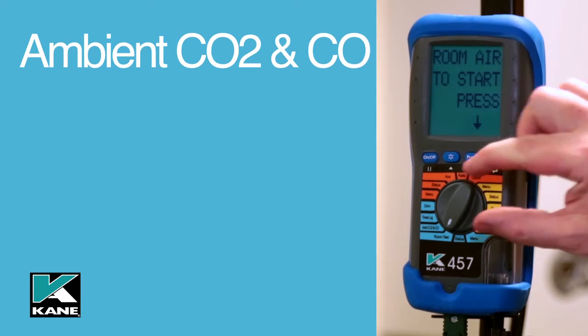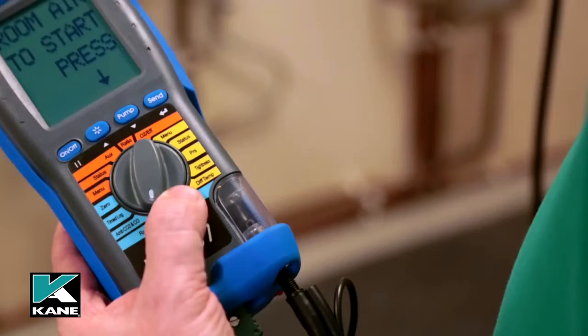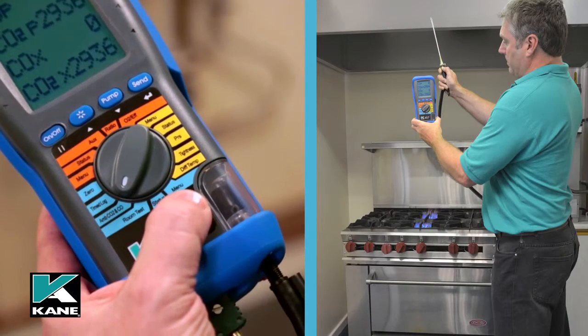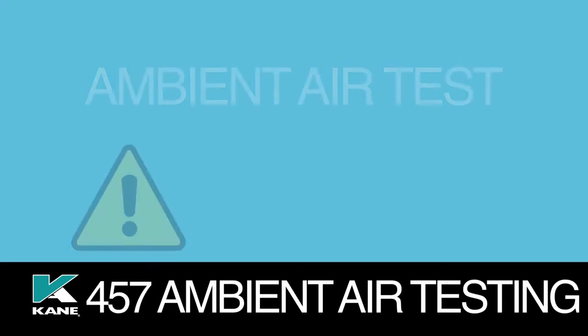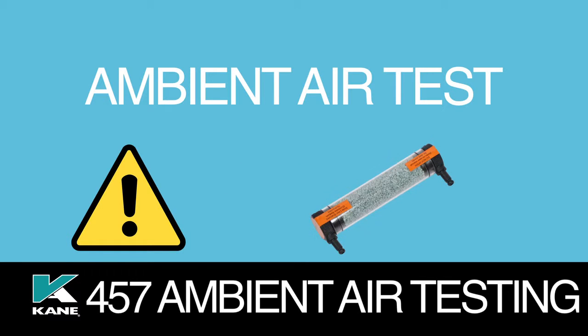Selecting the next function on the rotary dial, Ambient, CO and CO2, allows you to monitor real-time and maximum CO and CO2 levels, and could be used by commercial catering engineers when monitoring ambient levels of CO2 in ppm, parts per million. Note, before carrying out this test and to ensure accurate ambient measurements of CO2, the KANE457 should always be zeroed using a zero cal capsule. We shall demonstrate this in a few minutes.